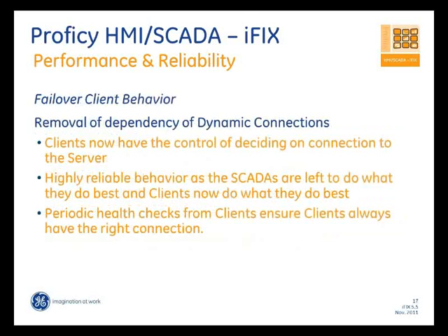The other is really the client behavior in the new iFIX enhanced failover environment. We just had a lot of complaints around clients flip-flopping between SCADAs, or clients being stuck on a particular SCADA when you go to a maintenance mode, or when the servers fail over.